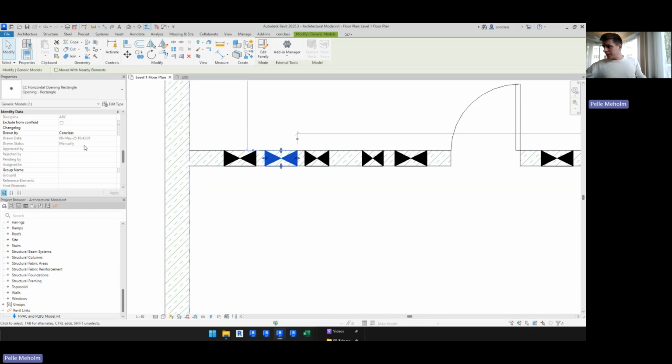Is there a limitation or a suggestion on the maximum number of openings created by a single filter? I have a project that has over 3,000 openings, which sometimes struggles to update in one go. Well, in one go, we recommend updating up to 1,000 openings. If you do it on your entire project, then your hardware is probably going to have some trouble.